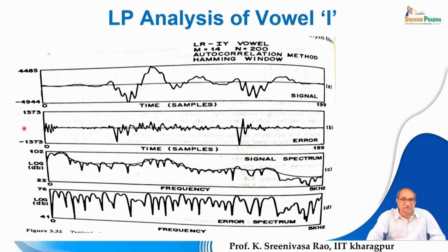So, we do not have any previous sample. Therefore, here we have to guess the sample amplitude randomly. So, that leads to error. And then when you come to the first sample, the 0th sample is available, because it was just observed. So, that becomes your history, and with that knowledge you have to predict the first sample.